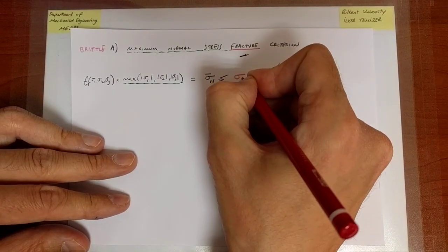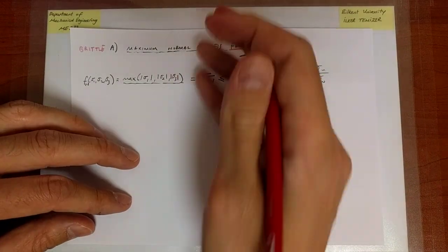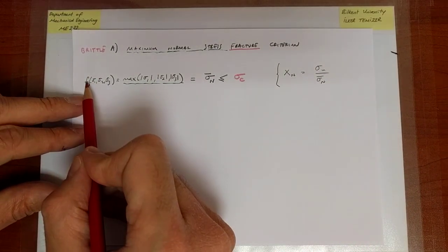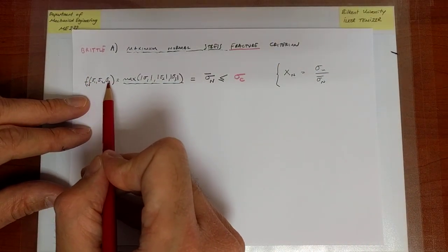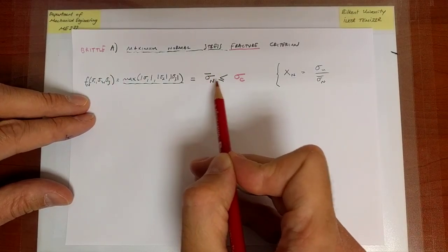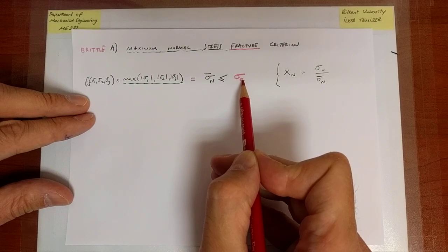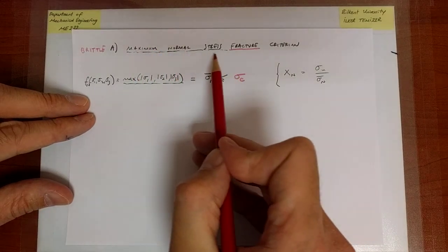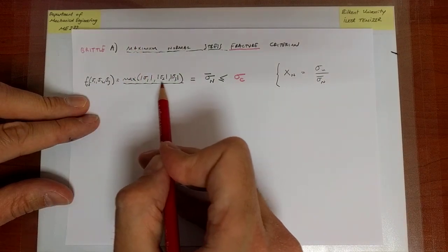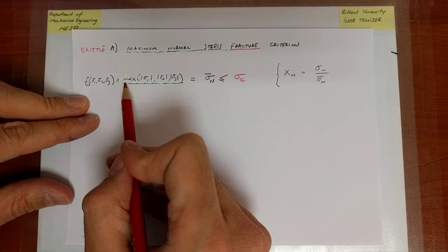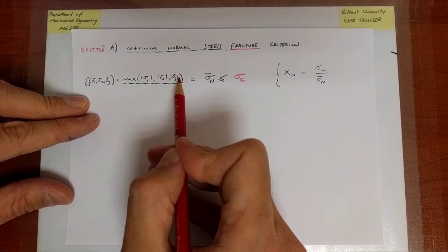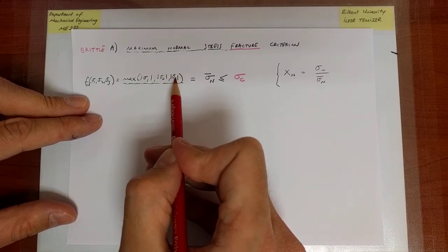That is, if you like, as yet unknown, because that is the form of our stencil. The stencil says, you give me a function that takes sigma 1, 2, 3, spits out an equivalent value, and I compare it against a critical value. Now, the name of the function suggests what I should be monitoring. I should be monitoring the maximum principal stress among the three, and I'm looking at the absolute value. We'll make a comment on that absolute value shortly.